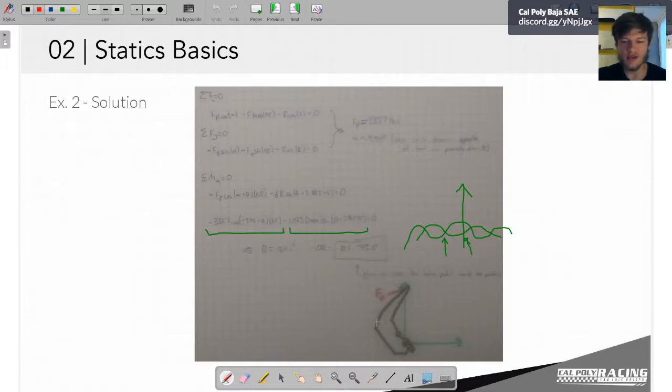This would say that somehow our driver is able to push on the pedal with a force of 3,000 pounds, which we know isn't possible. And it also means that this pedal would have to be at an angle of 45 degrees cocked backwards, which we also know is impossible. So it means that his FEA was conservative and that the aluminum bracket that he made should never fail.